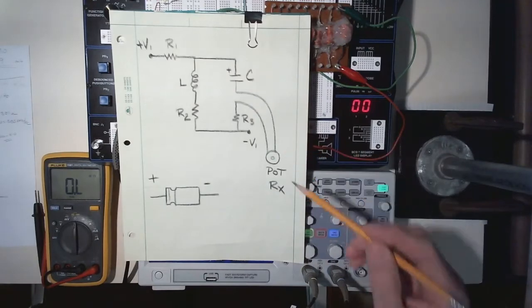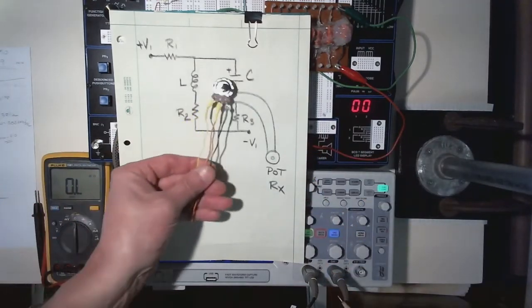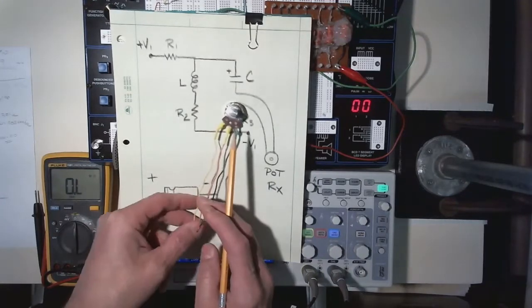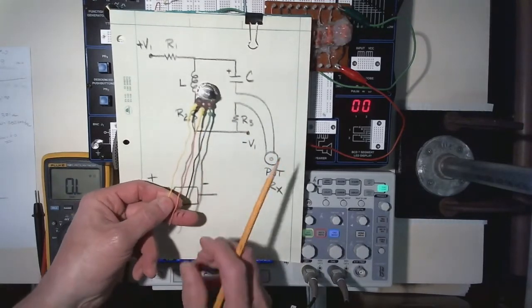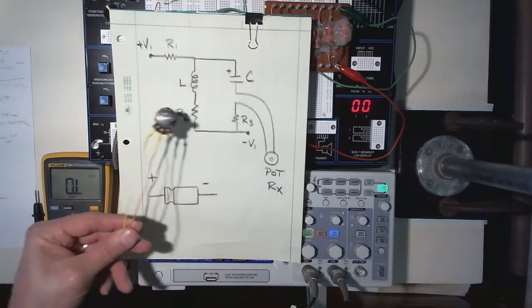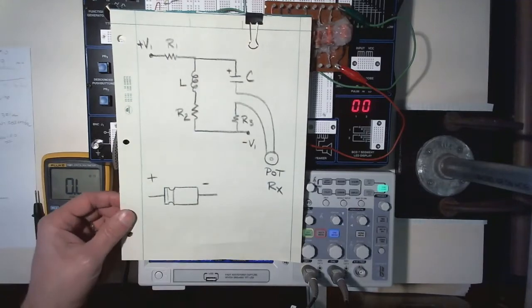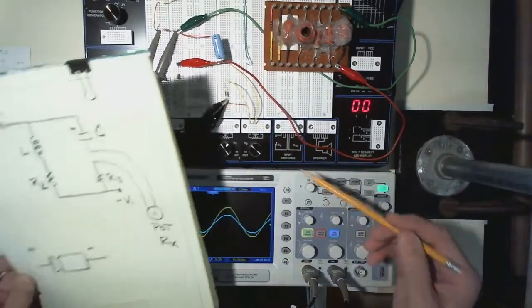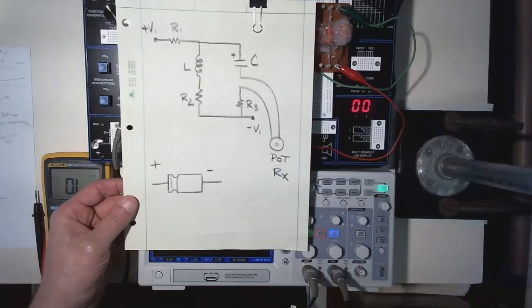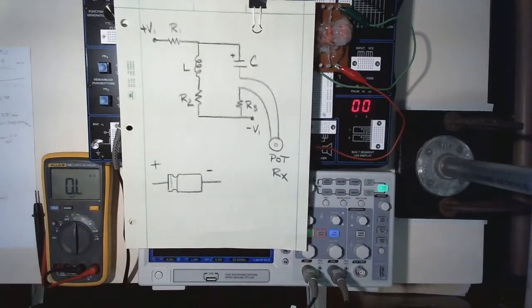I've got the potentiometer. We could have put in a potentiometer something like this. You've used these before. We just use the middle leg and one of the outside legs, so maybe these two legs here, the orange and the black, that would work out fine for us. I've actually used the built-in potentiometer here. It'll be a little more convenient, so I've shown that we come down with the wires there and use that potentiometer. And again, I'm going to spend a little more time in this lab pointing out some of these tricks and tips and things that you should know as you spend more and more time around these things.